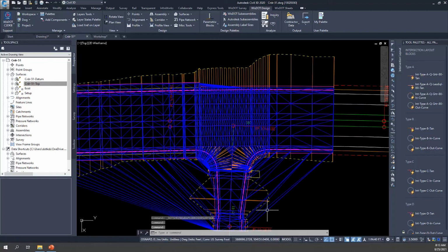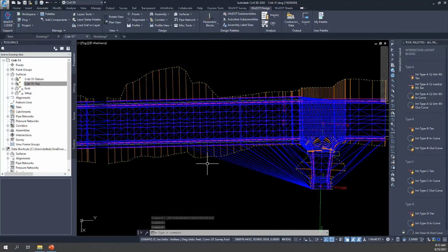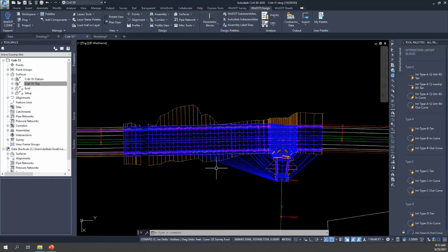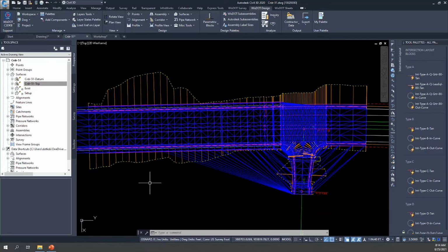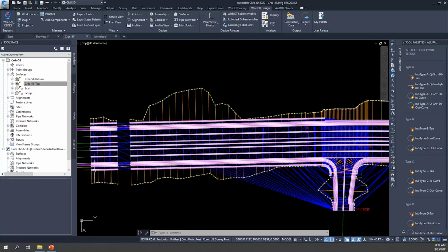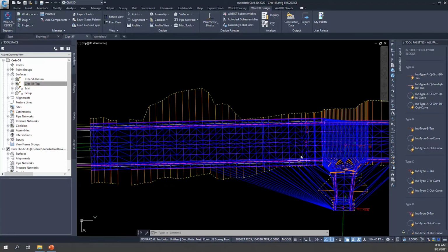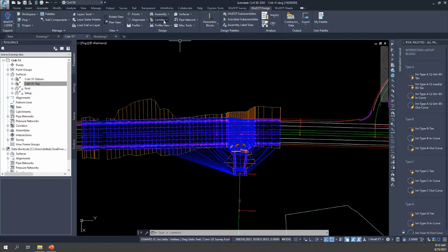You're probably thinking, oh, big deal. The top surface, usually I can just use the out-of-the-box shrink wrap. Very true, but the out-of-the-box does not account for gaps, so keep that in mind. But the real kicker usually is the datum boundary, because the datum boundary almost always requires you to do the interactive trace around your intersections all the way around and then cross your fingers, hope it actually works. This should greatly simplify that process.